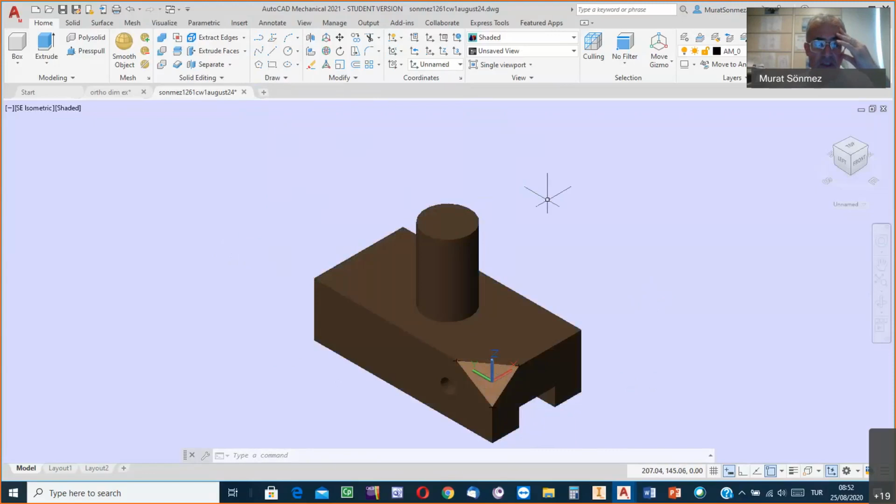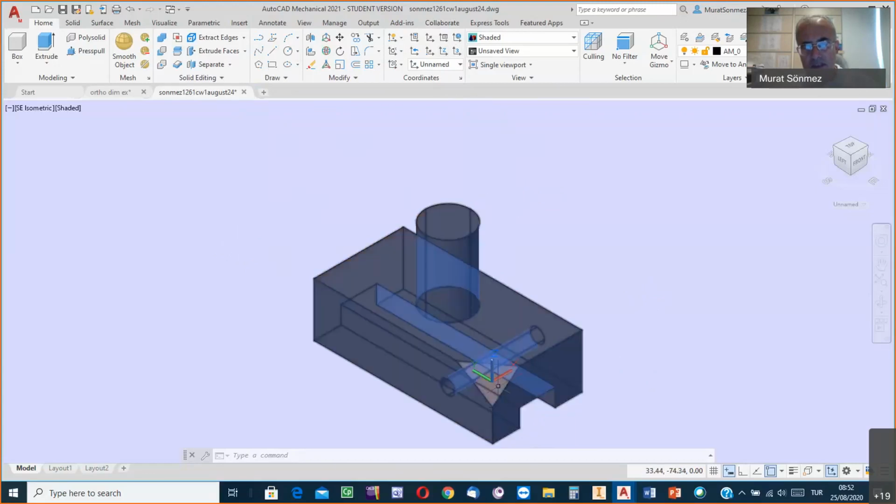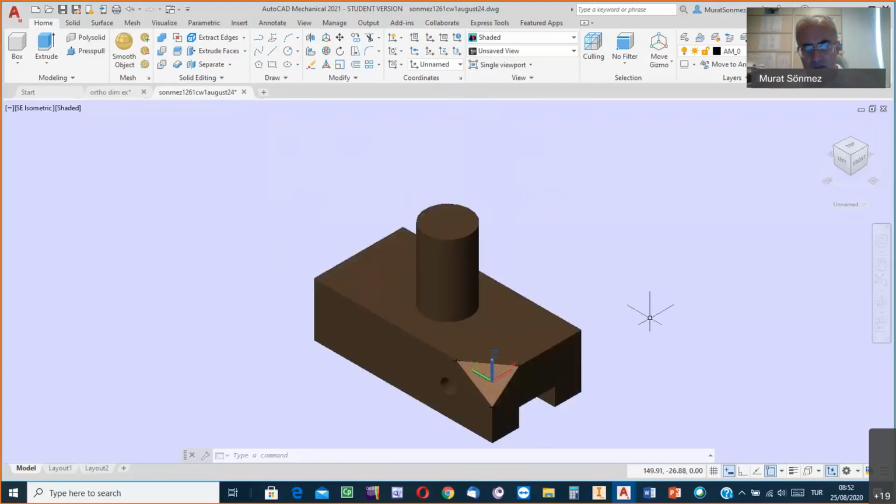If you know the coordinates of the characteristic point of the new feature to be added with respect to a certain specific point, then first use these tools in the coordinates panel to bring the coordinate axes to their origin at that point.